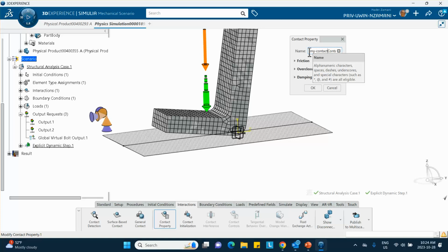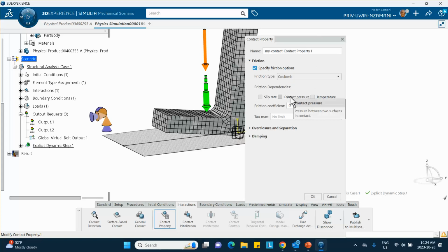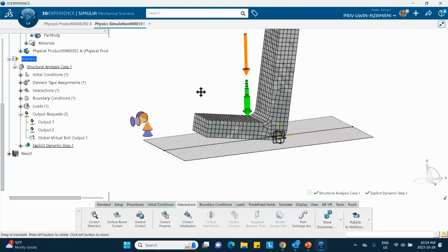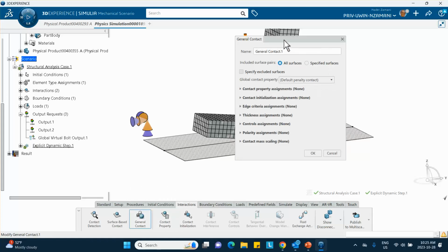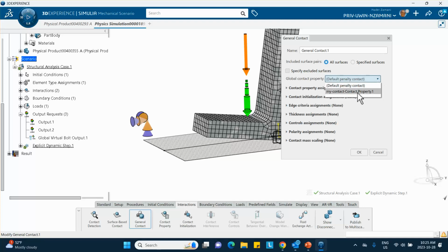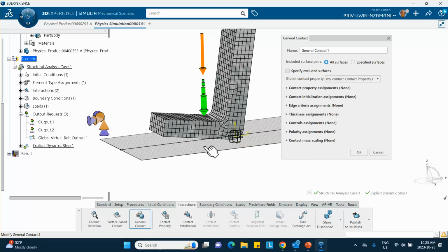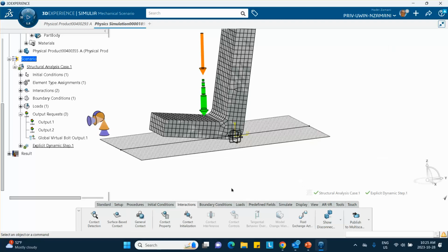And I think, as I pointed out, the fellow takes this friction coefficient to be 0.1 if I'm not mistaken. So I'll use the same thing, 0.1. If it's something else, just put the right value there. All right, good, 0.1. And then we do general contact with the contact property that I put in, okay? And it will figure it out by itself. I was missing that. That's why this went through it. Okay. So pretty much it.